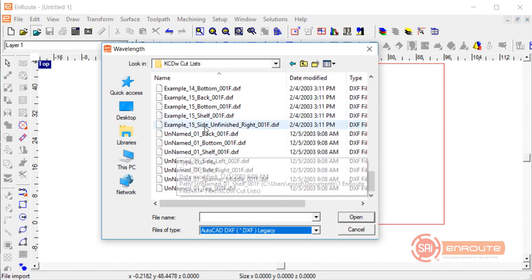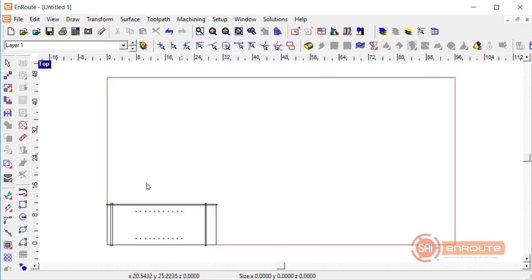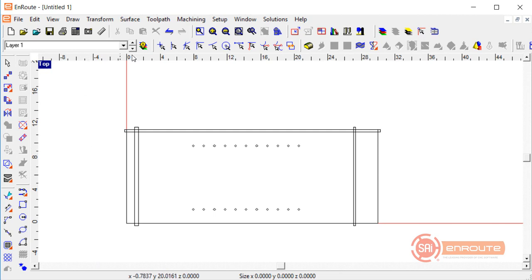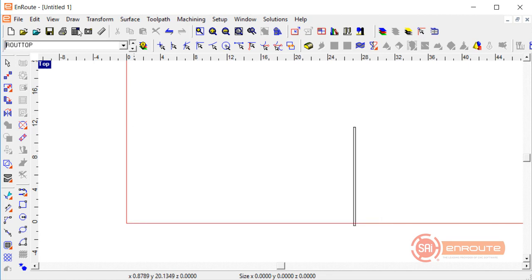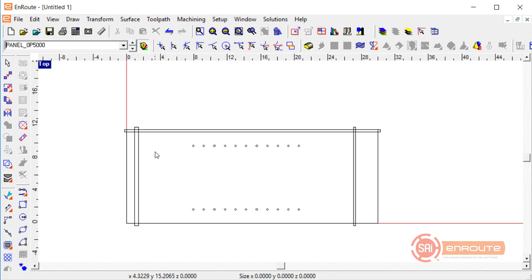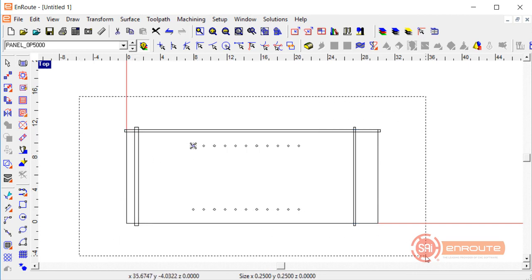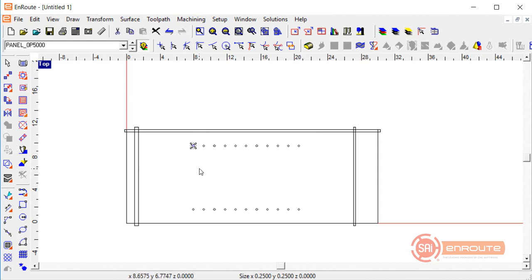And usually if you're looking for this and you are doing cabinets, a right side or a left side will have most of the layers you need. But you can see here all the different layers and each of the different types of toolpaths that might be required to toolpath those layers. So I need a perimeter cut, I need pocketing, and I need drills here. That's the 3 kind of toolpaths I need for this file.